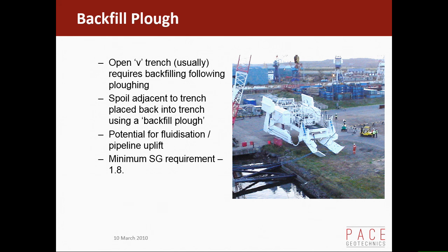One point to make is minimum SG requirement. The reason for that is, as you push particularly a sandy, silty type soil back into the trench, it ends up as a dense fluid, if you like, and if your pipeline isn't heavy enough, it floats in that fluid. So you push the material back, your pipeline floats up, and you're stuffed. Basically, you've done all that work for nothing. And I've seen that happen on several occasions as well.